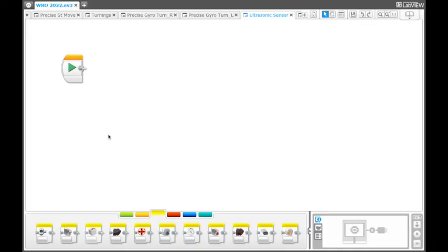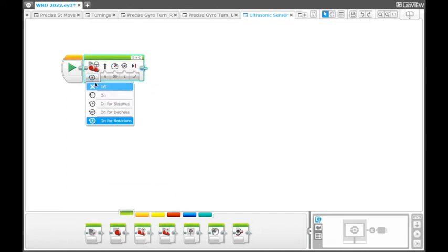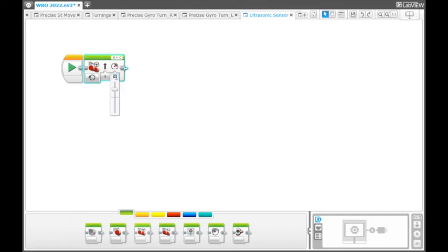In the previous stage, you must have seen that I detected the grass using the ultrasonic sensor, and then I cut the grass. So let's see how you can detect an object using the ultrasonic sensor. For that, you have to move the robot forward on unlimited, and in this case I would suggest that you use a little less power when you are trying to detect any object, because objects like bad weeds or grass are little small, and if you move your robot very fast, then you may not be able to detect those objects. So move a little slow for that.